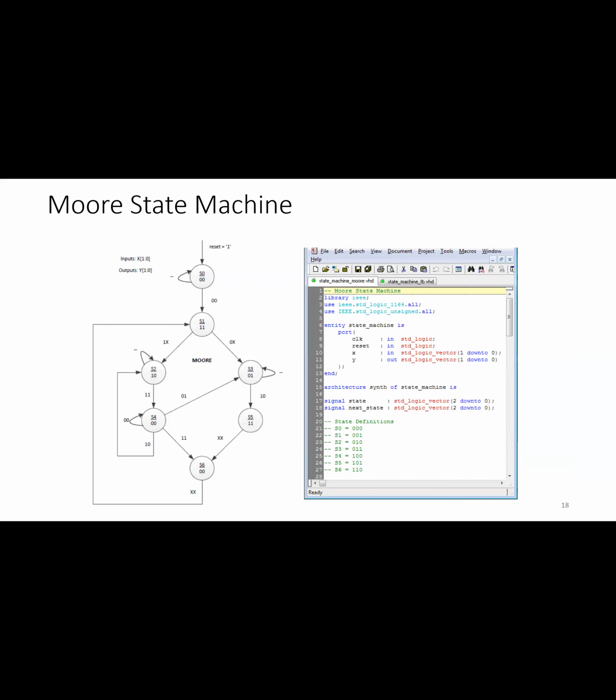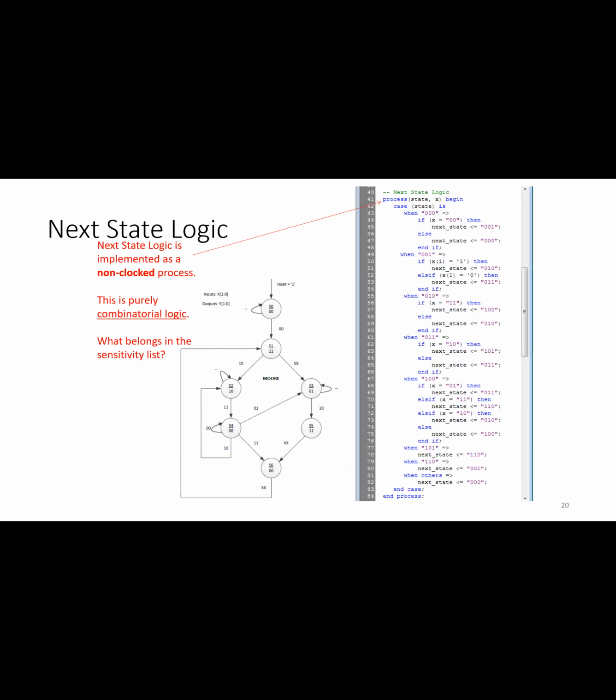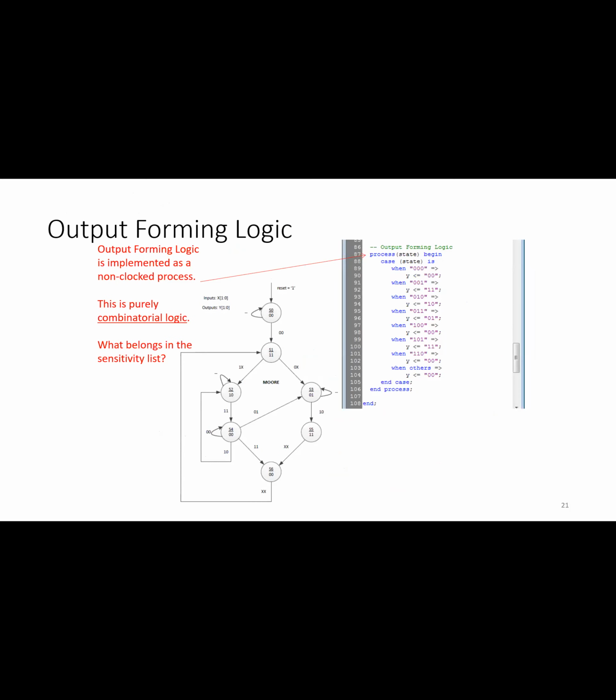In the Moore machine, the output is beneath the state number, and it depends on the state. It is independent of the input. The input is just to move me from one state to the next. And we had the example, the state, the next state part, and the output part. And as you can see, for each state, I have a certain output.